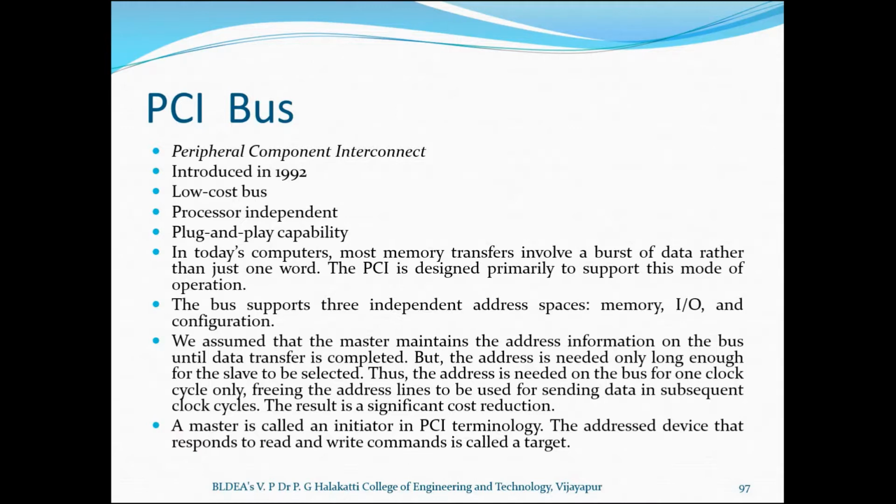So, it has a standardized format which it can use independent of any processor. Devices connected to PCI bus appear to the processor as if they were connected directly to the processor bus itself. They are assigned addresses in the memory address space of the processor.